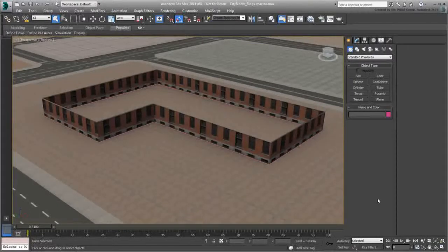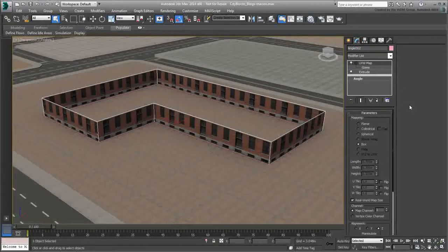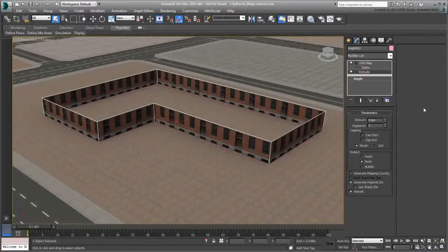Use your own file or the file named cityblocks-buildings-macros.max that's been provided to you. Select the street level extrusion and go to the Modify panel to take a look at how it was created. Initially, it was created by duplicating an existing 2D spline as a reference. Then, an extrude modifier was applied using a preliminary height value. Ultimately, you have also settled on disabling capping options.